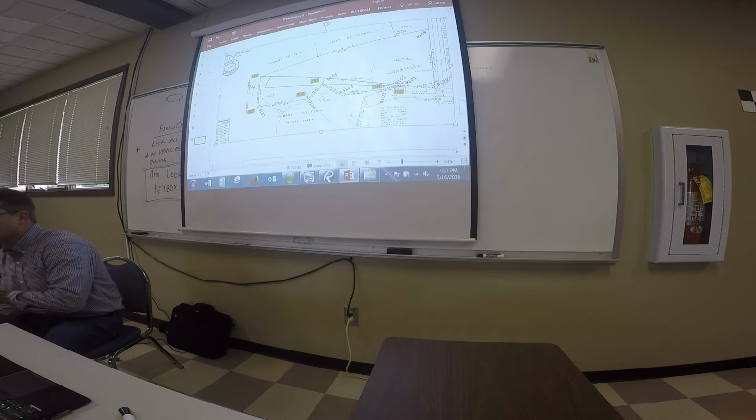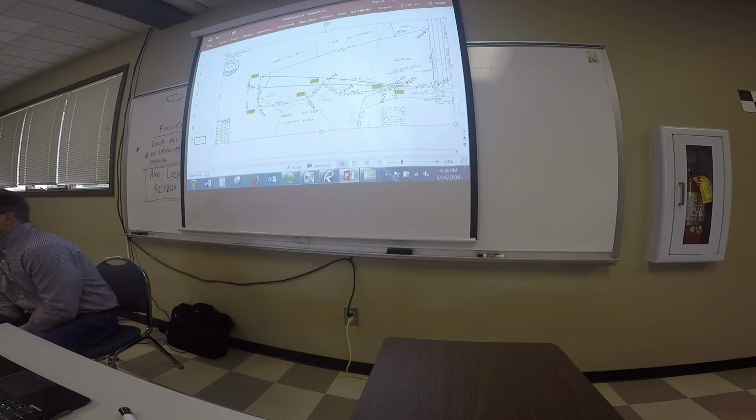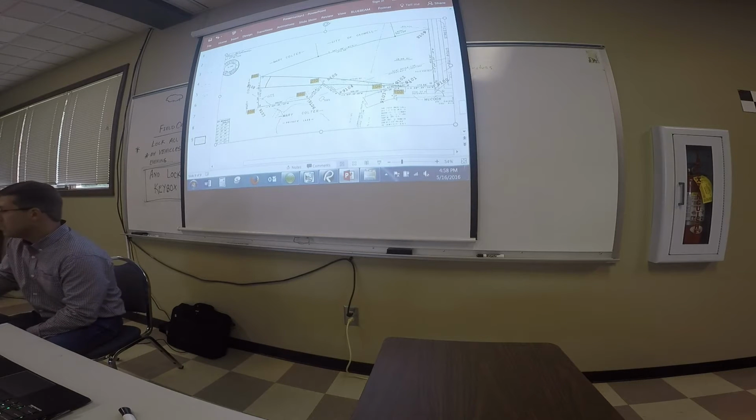Basically, Carlson Field to Finish is the software that we use to process what you guys do in the field. What that does is it starts with using your points sequentially and then goes into reading that code that you guys use and whatever numerator or number that you put at the end of that code. It uses that as a sequencing thing to connect those lines.